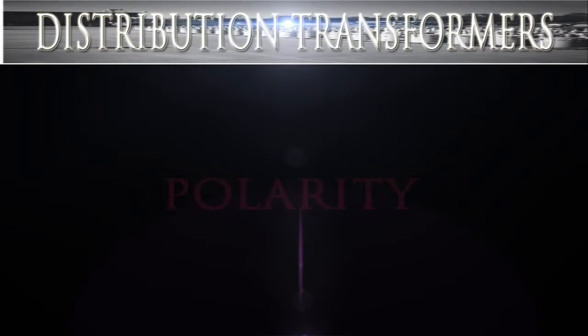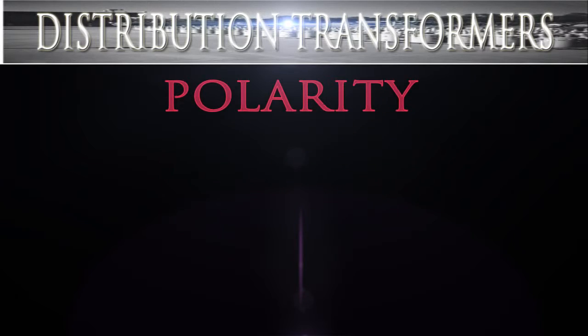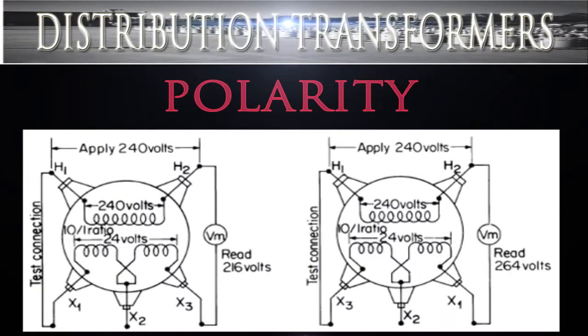In connecting transformers, it is important to know the polarity of the transformer terminals or leads. In building transformers in the factory, the ends of the windings can be so connected to the leads extending out through the case that the flow of current in the secondary terminal with respect to the corresponding primary terminal is in the same direction or in the opposite direction.